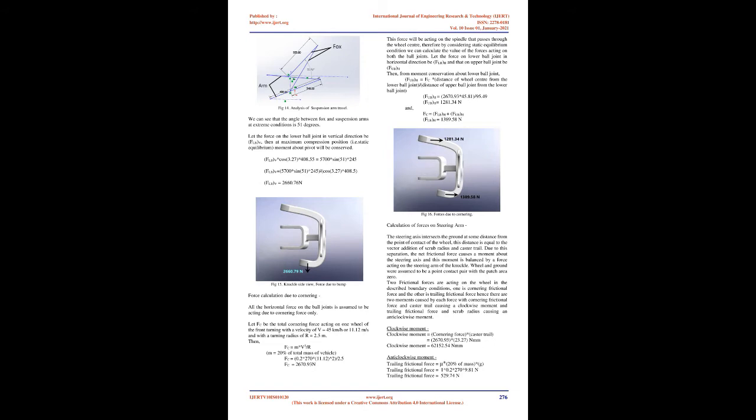The complete design process of the knuckle can be divided into the following steps. 1. Basic designing of the knuckle according to suspension hardpoints. 2. Calculation of forces in different boundary conditions. 3. Analysis of the knuckle. 4. Topology optimization of the analyzed knuckle. 5. Final designing according to optimized data. 6. Analysis of the final knuckle.